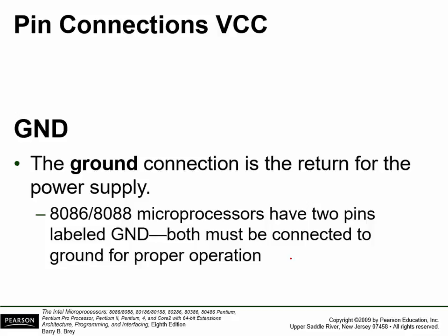Now, I've had problems with houses, especially in rural Malaysia. I used to live in Kelang 20 years ago, and grounds were very uncommon in houses. They just let them float, and I had all kinds of problems with lightning taking out modems and things like that until I hooked up a wire to my computer case and stuck a 2-foot steel pipe into the ground with a wire attached to it. The term ground literally means it's tied to the dirt outside, in an ideal case.